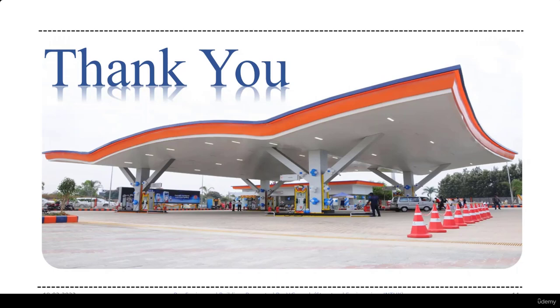But in fixed base, will the section be more economical? Probably you are talking about the column. Okay, fine. In some cases it will be yes, in some cases it will be no. Because in fixed base we cannot use a tapered section, because the bending moment will be positive at the bottom, then it will go to negative, and then again be positive at the top. We cannot taper the section like that, right? So we have to use a straight section, which may be economical sometimes, but in most cases it will be uneconomical.